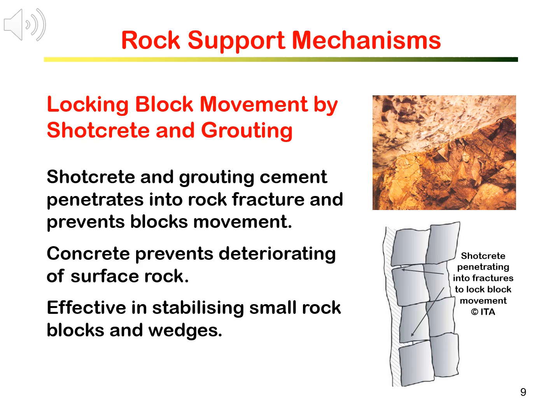With the formation of concrete supporting lining and the locking of rock block movement, shotcrete is indeed very effective in stabilizing small rock blocks and wedges at excavation roof and side walls. By combining rock bolts and shotcrete, unstable large blocks are fastened by the bolts, and unstable small blocks are supported and locked by the shotcrete.